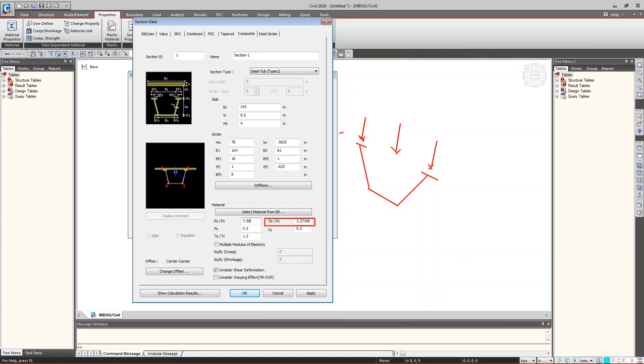That is, the slab doesn't have the structural stiffness yet to transfer the forces, right? So when the slab comes into the picture, the slab will act as a structural member over the girder, and all the other loads after the composite property has been activated will be taken by the composite stiffness, right?